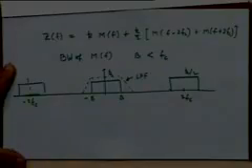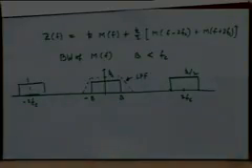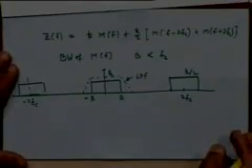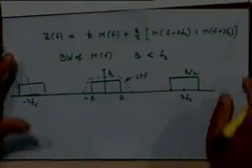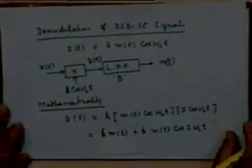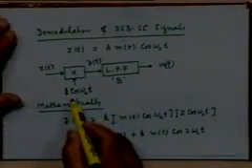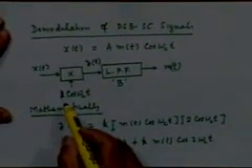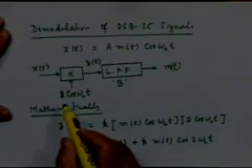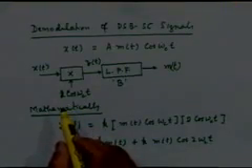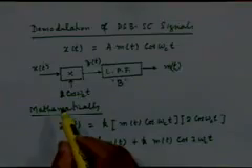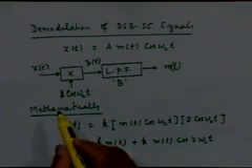So that's a demodulation. Looks simple enough. There is a small complication which you should be aware of. The demodulator, if you look at it, requires a local carrier, right? At the receiver, I must have a replica of the carrier that was used at the transmitter. Now that doesn't appear to be a big deal, but you must remember that there is a requirement here.